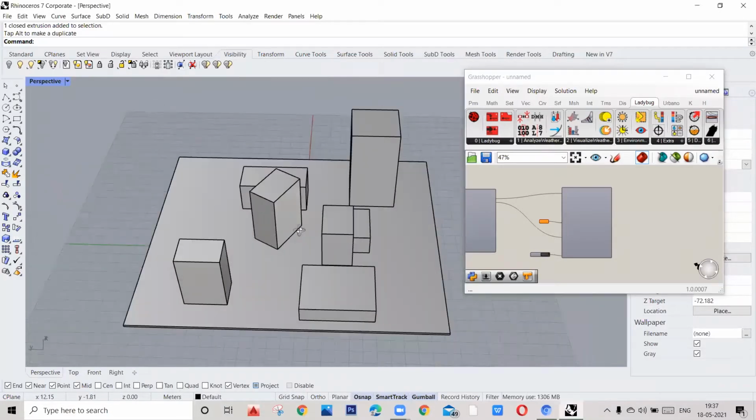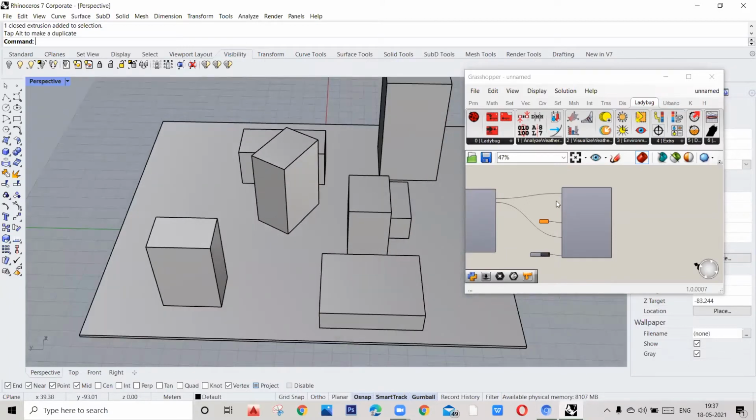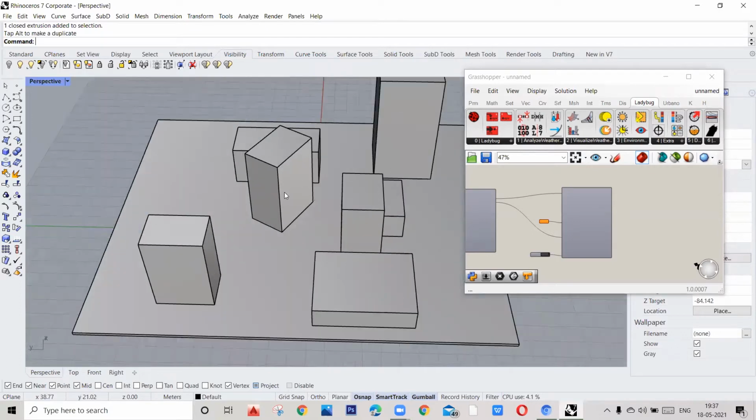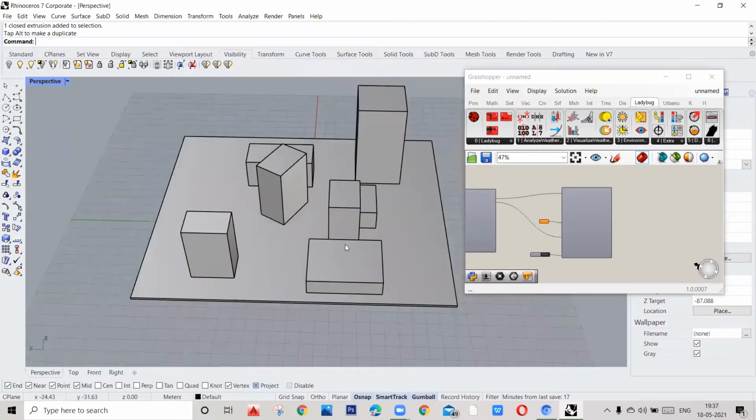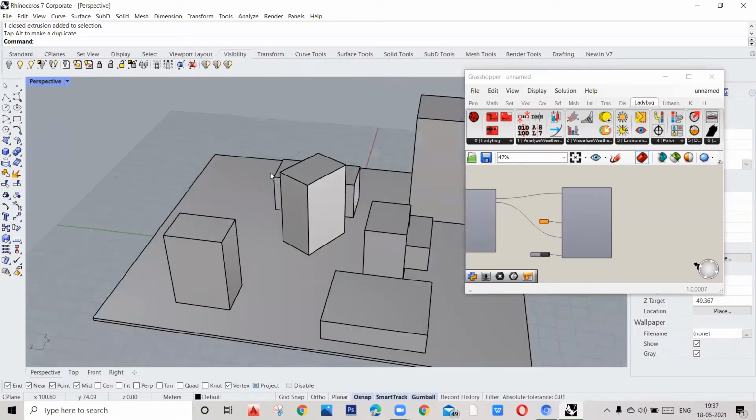Hey guys, for this tutorial we'll be using Ladybug, same as we did in the previous video. Previously we visualized weather conditions using graphs, and we tried to create a graph of wind and sunlight analysis. For now, we'll be using a 3D contextual model and try to get the daylight effect and exposure on the surfaces, vertical surfaces, and also over the land and the spaces between the blocks.